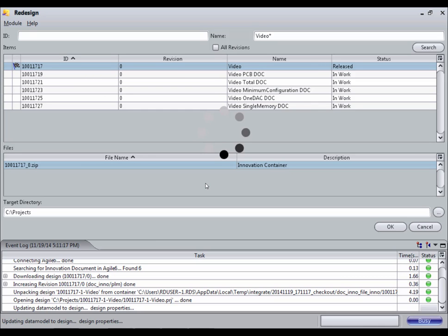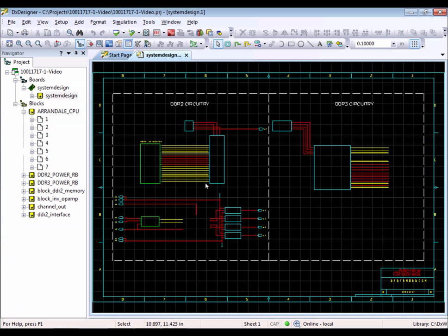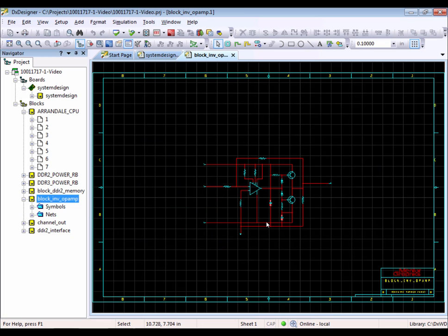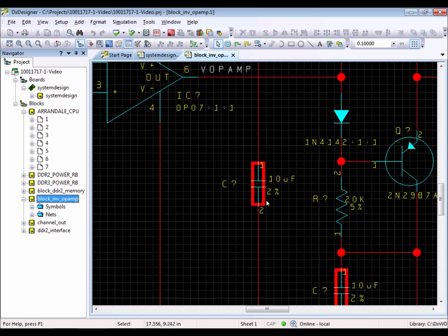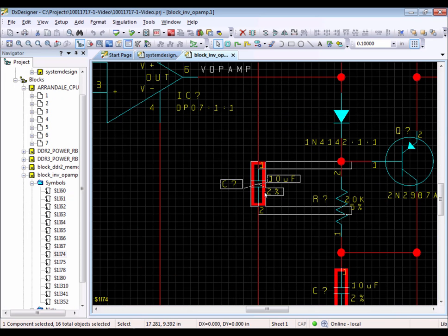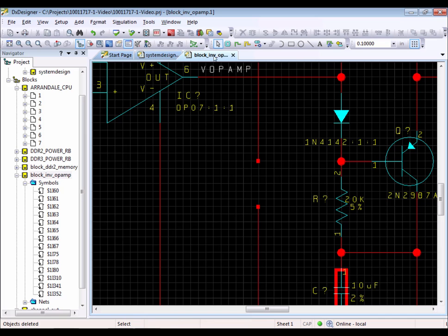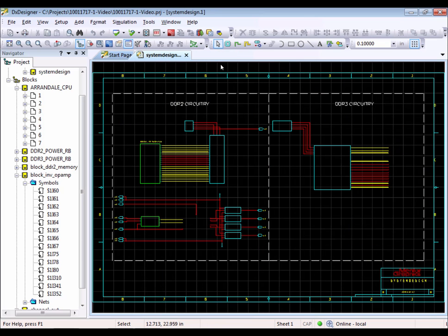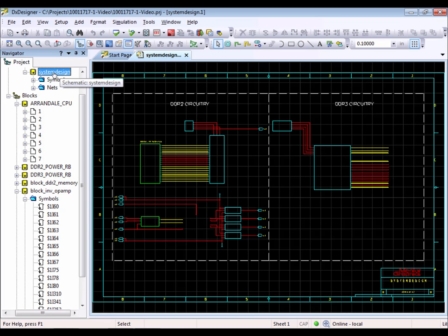The next step would be now to change the design and upload it again with the module save to the PLM system. In our demonstration, we delete now one capacitor. Because we use a hierarchical design with reused blocks, this will lead into the deletion of 4 capacitors in the bill of materials. After that, we start the module save once again.